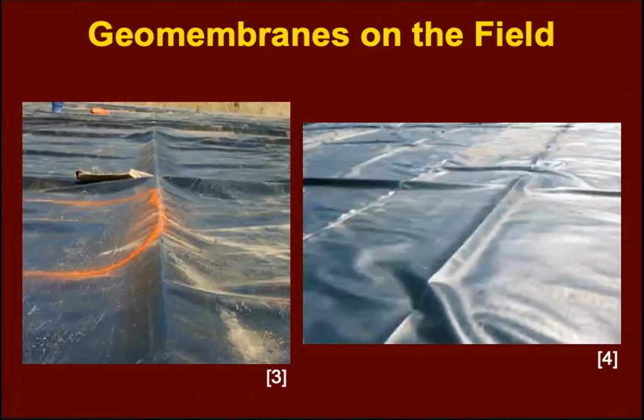So ideally, geomembranes are impermeable, so no advective flow can develop through them. But the problem is that geomembranes have a high coefficient of thermal expansion. So when they are laid in the field and are exposed to sunlight, they expand and develop wrinkles to accommodate the extra material. In addition, even when we have good quality assurance, holes will develop in the geomembranes, especially in the wrinkles. This especially happens once a layer of cover soil is placed on top of the geomembrane and construction operations are still being performed on top of the liner, which will damage the geomembrane.